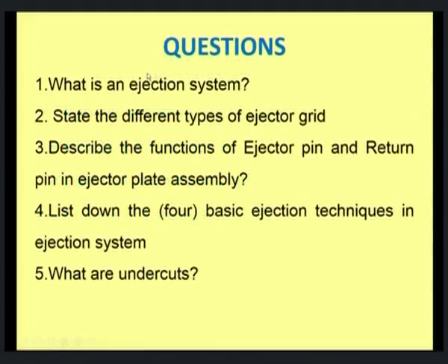Now, after looking into this episode, these are the questions the viewers should try to answer. What is an ejection system? State the different types of ejector grid. Describe the functions of an ejector pin and return pin in the ejector plate assembly. So, this ejector pin and return pin are the two main pins that actually move this ejector plate in such a way as to eject the part out. List down the basic ejection techniques in the ejection system and what are undercuts.